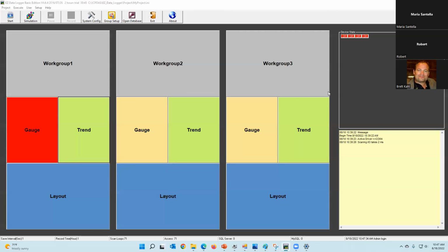If you have CANopen, DeviceNet, J1939, Profibus, Profinet, or Ethernet/IP, all of those different protocols to Modbus are on individual modules, not one generic module. So if you can let us know what protocol you need to convert to Modbus, we have gateway solutions for almost all of them.